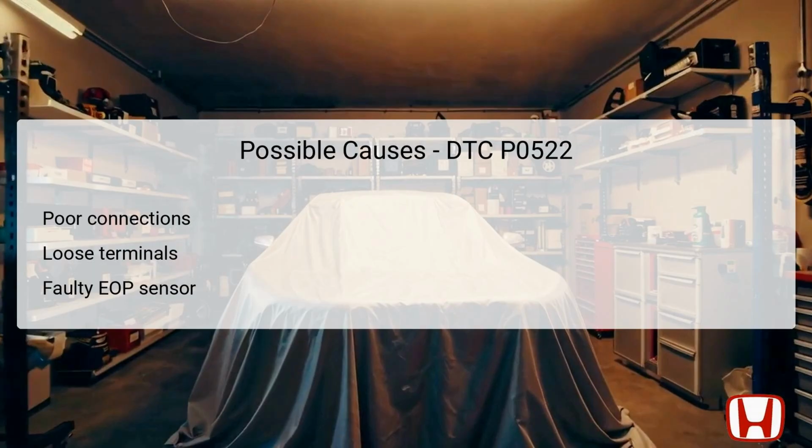Additionally, the EOP sensor itself could be faulty, meaning it is unable to accurately measure oil pressure. Mechanical issues such as low oil level or debris blocking the sensor could also contribute to this error. It's essential to evaluate these possibilities methodically to identify the root cause accurately.